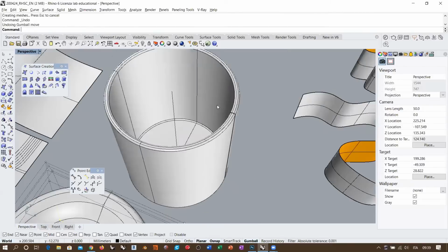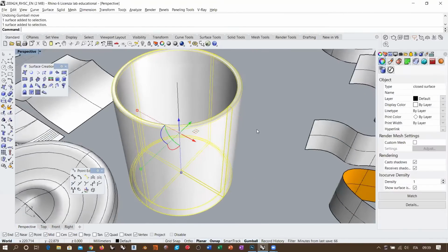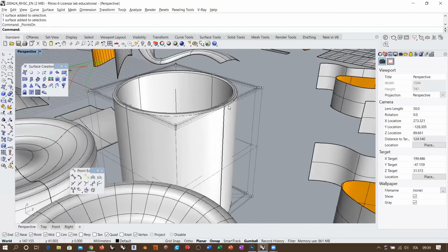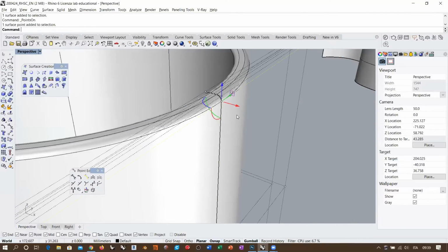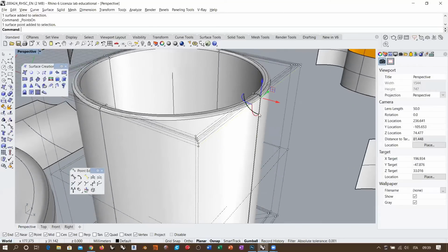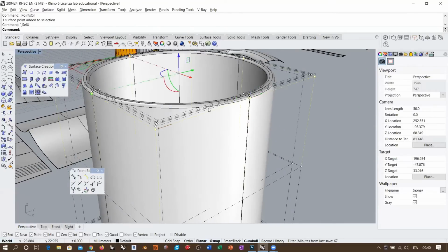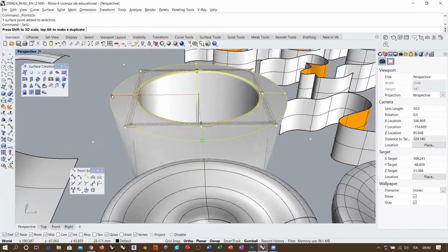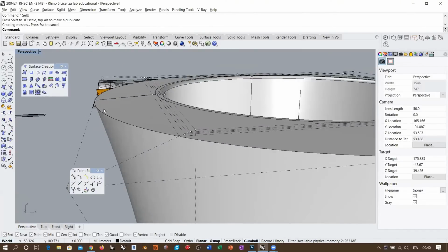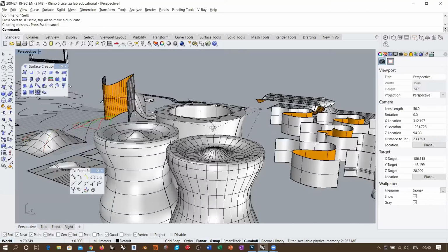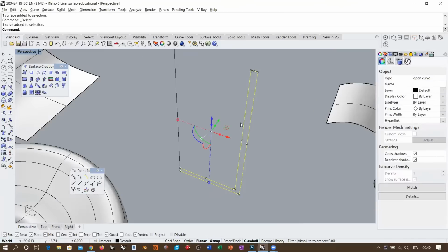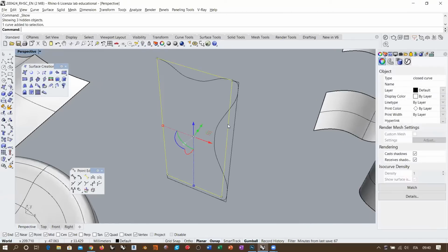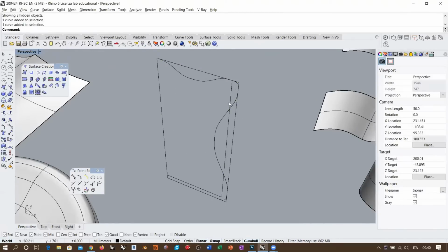So this is still a surface, but as we created a profile with this tangency continuity, we could get some discontinuity the moment that we move this set of points. For example, if I select this and select all the U direction, and I try to do this, you see that I am creating a crease along this edge. So this is not the best way to do this. That's why I tend to use the NURBS curve in order to create also this simple shape.